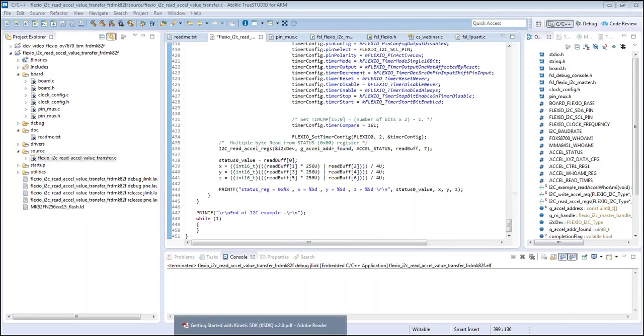And so you can see I have some other hardware here, and one of the other examples that we talked about is using the Seeed Studio expansion boards. And the pins, if you look to webinar 2, we have some nice graphics that show all the pins that the FlexIO goes to. And the advantage of the FlexIO is, even though it may not go to a defined I2C pin in the Arduino form factor, you can leverage other connectors, other places, and connect the I2C.